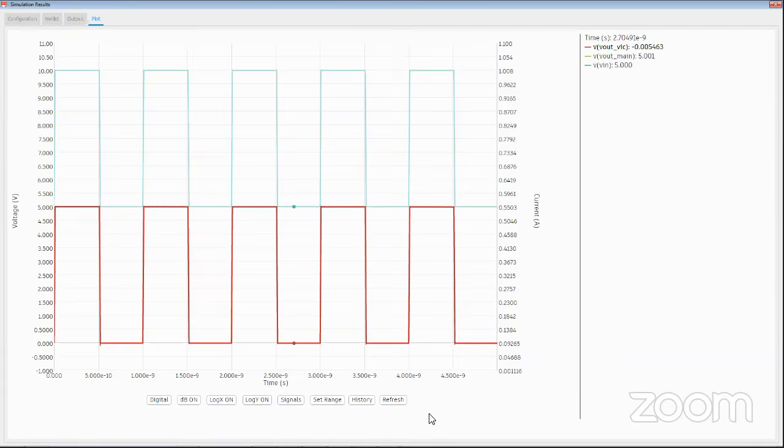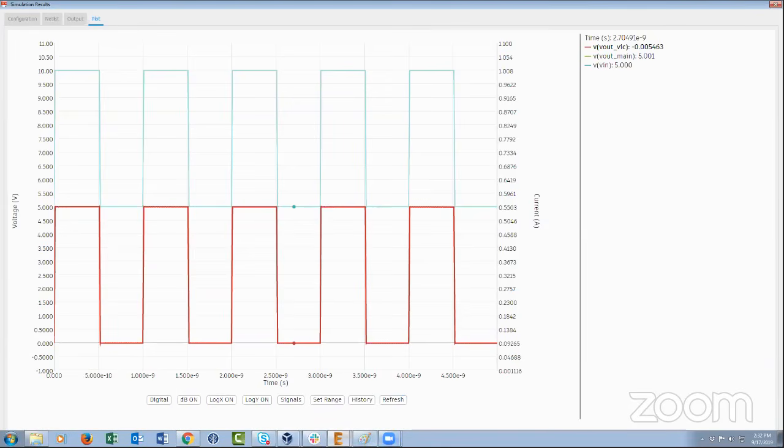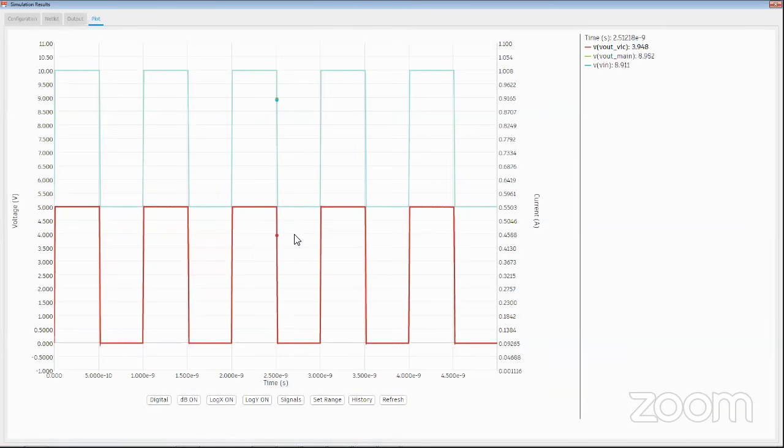And that's because capacitors, as you guys know, block DC. So in your circuit, you're not expecting that nearby conductor to have an exact replica of your input signal. But that's what happens when you think about these effects and you see them taking place. So if you ever observe something weird in a layout or in a design that you weren't expecting, more than likely it's some capacitive or inductive effect that you haven't taken into account.